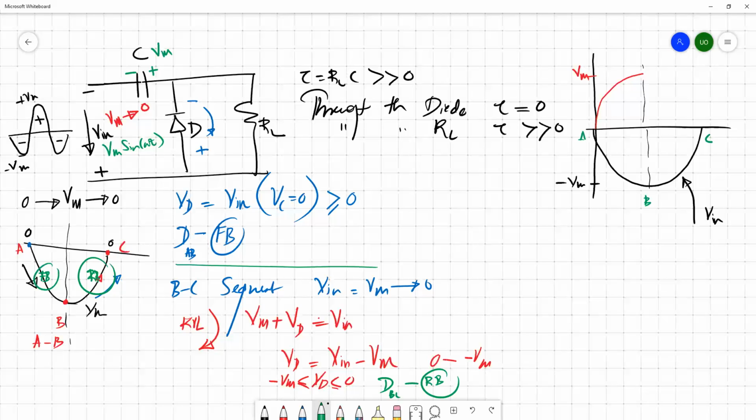So then we have a circuit where you also have a load resistor. So what happens? The diode is reversed and it's open. So then the voltage appears across the load, and the diode is no longer there. The RC time constant is very high, so the capacitor doesn't discharge through RL. Whatever energy is stored across the capacitor remains as it is.